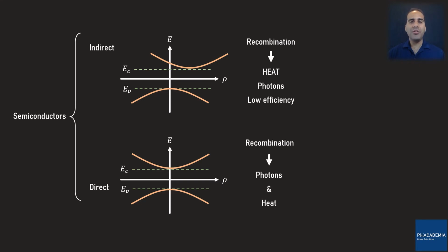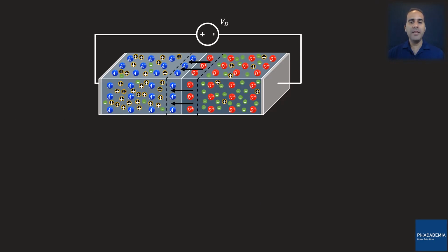In this lecture, you are going to take a closer look into the light emitting diode world and learn how an LED operates. Here I have a p-n junction diode, which is made of a direct semiconductor such as gallium arsenide. As I already mentioned, an LED emits light during the recombination process. Therefore, it is logical to promote the recombination process in an LED to gain more light.